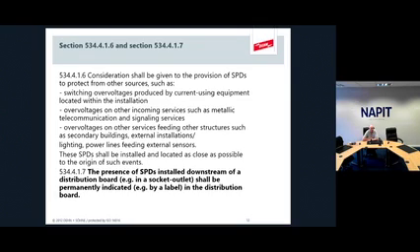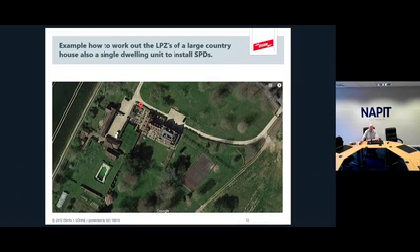And then the wording in there is that these SPDs shall be installed and located as close as possible to the origin of such events. So you want to nip the surge in the bud before it can do any damage throughout the installation. And then finally, in bold, you're going to have some labels, because when you come to do your IR tests, the surge will see it, dump it to earth, and you're going to get a mad result and think there's a problem. There isn't. It's just that the SPD is sitting there dumping that surge to earth.